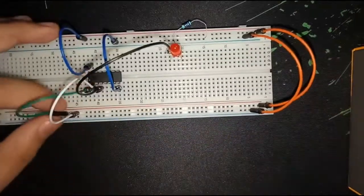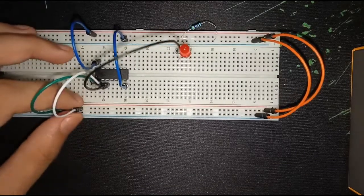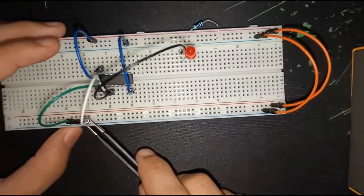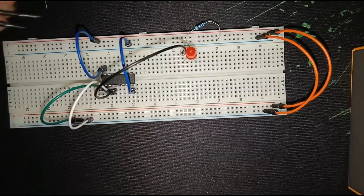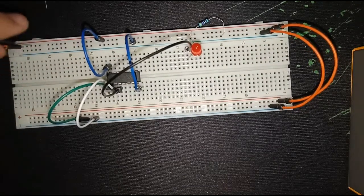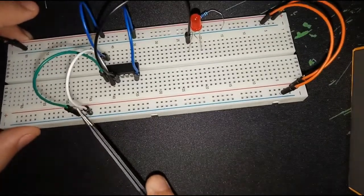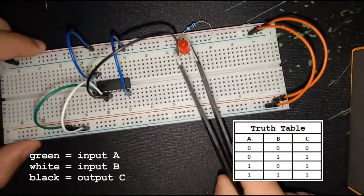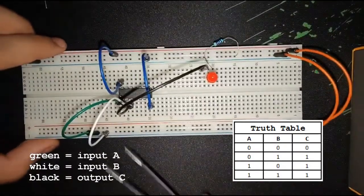So we will see, or we will prove, the truth table. So from that example in our hands-on, we have all 0, meaning all negative, does it light up? So therefore it will not light up. So we will connect it to the battery. So we will know if it turns on. So therefore it does not turn on. So why? Because the truth table of the OR is, if what you input is all negative or all false, your output will be false or 0. So therefore it switches off. So it does not light up.